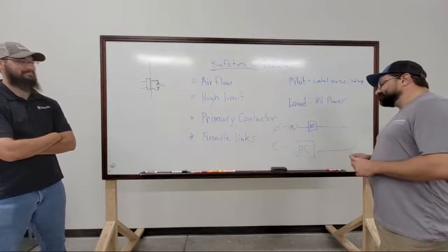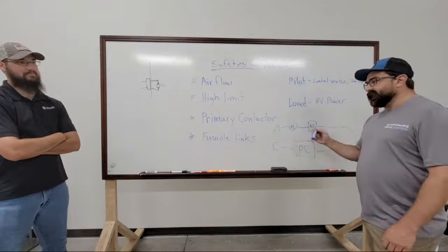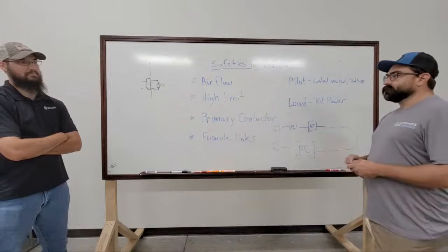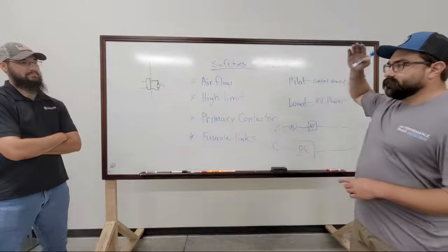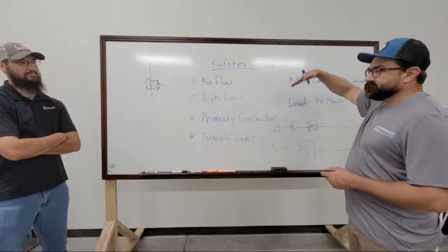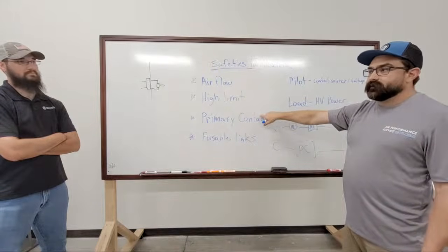But yeah, that primary contactor, if you don't understand its function, can play havoc on people when it comes to troubleshooting. Because say you have an SCR, you can be sending all the current, all the signal you want to that SCR. If this primary contactor does not make, it's not going to do anything.